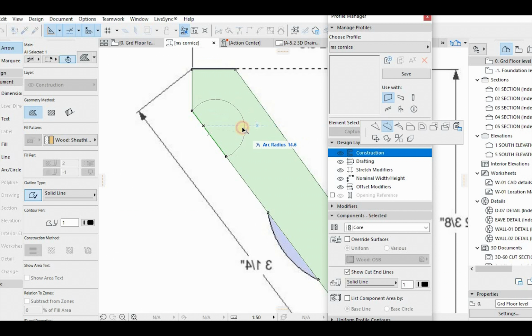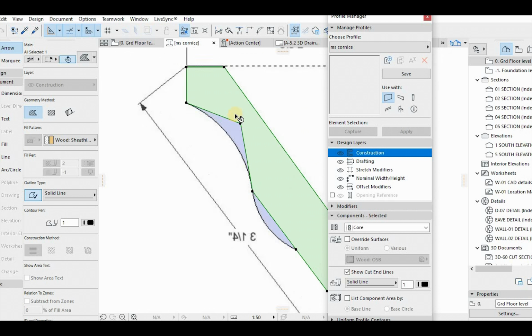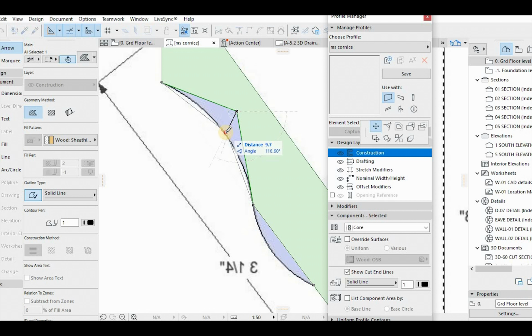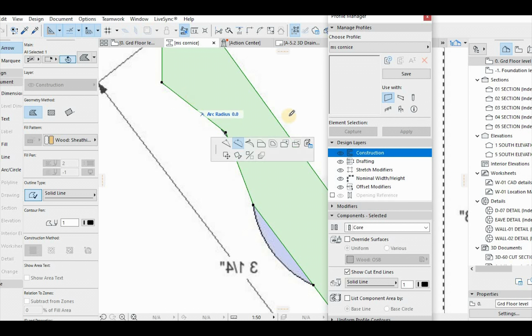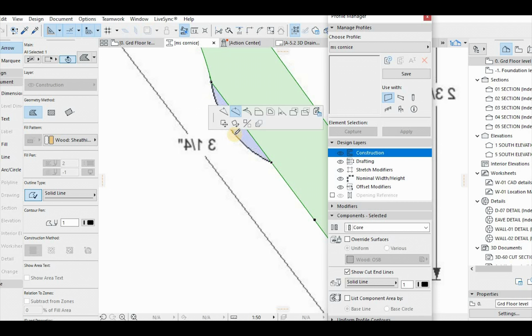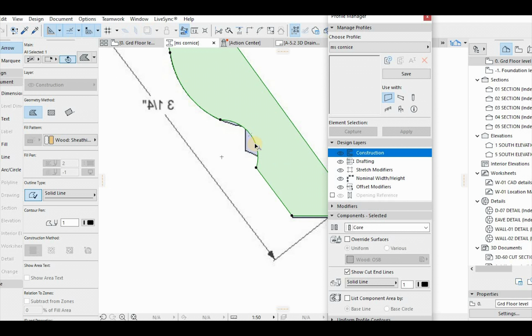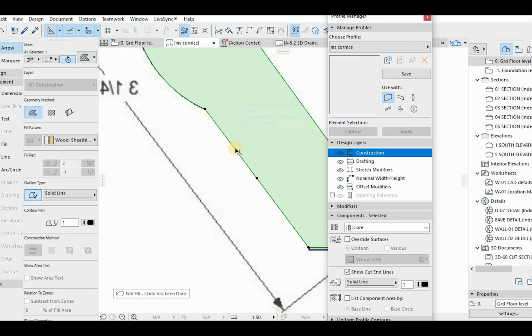Then you can spread it at any dimension you want, and use fill selection settings to assign building materials. Remember, I told you to draw with fills. Anything that's made of a fill is going to be extruded, so be careful and be aware of what you're drawing.